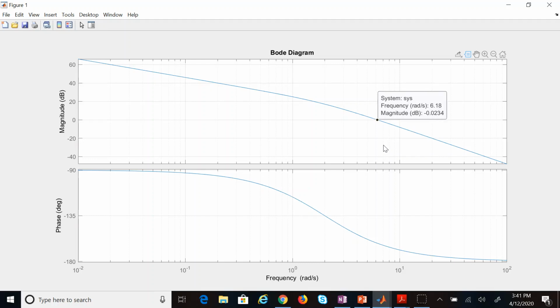That is the closest you probably can get to 0. And you see the gain crossover is 618 radians per second. And now we calculate the phase of the system at the very same frequency here. So we try to click at the same point. There are corresponding points. So we go to 618, which is here. And you see the phase right now is negative 162.